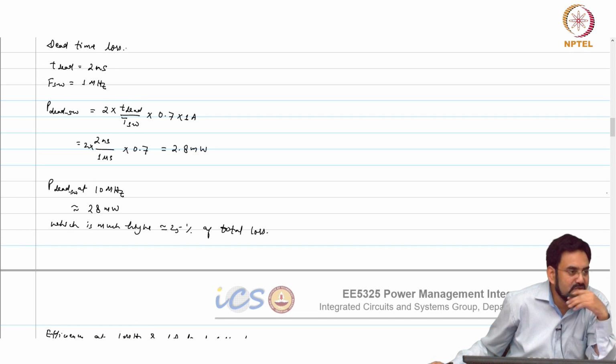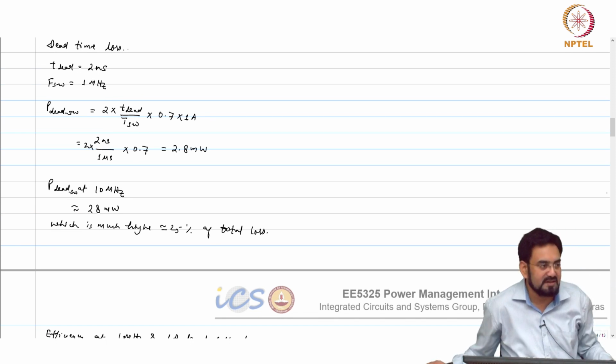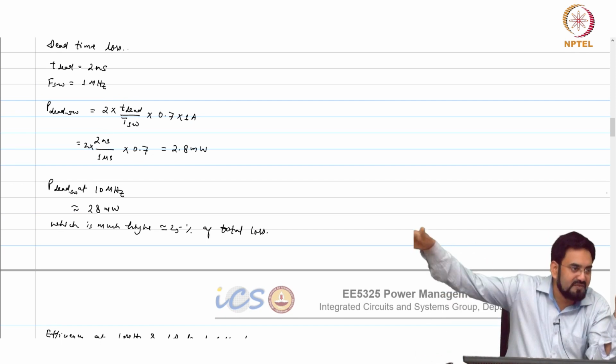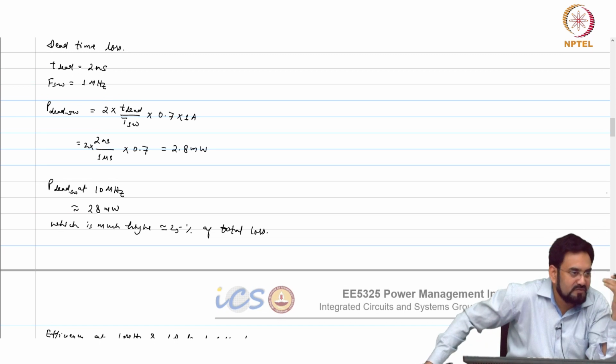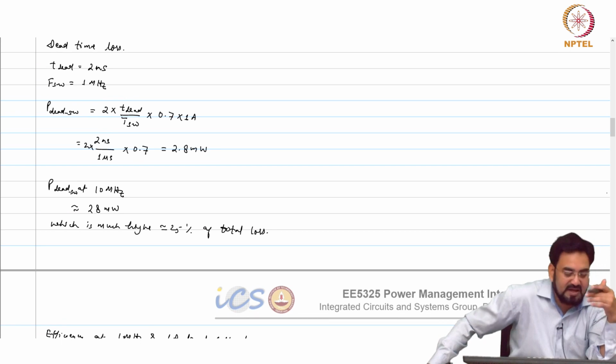That is why most DC-DC converters operated from a lithium ion battery, mostly used in cell phones, where the lithium ion voltage we know is like 2.5 to pretty close to 5 volt, 4.6 to 5 volt, so this 1.8 volt, or 0.18 micron, does not work there. You need 5 volt devices, and operating at 10 megahertz there is not easy if you want to cater to 1 amp. I mean, 90% efficiency is very difficult. You may achieve maybe 85, 86%.